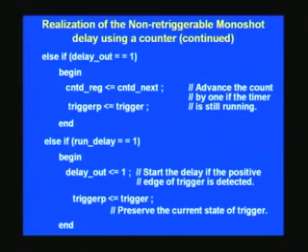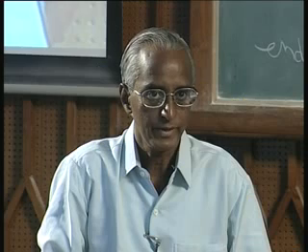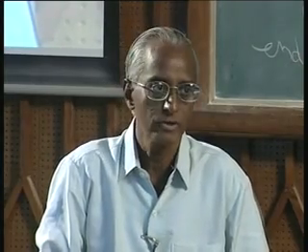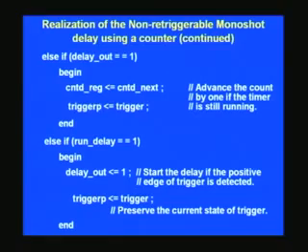So far we have seen how to write Verilog code for a simple D flip-flop, and then went on with a little more complexity by cascading 2 registers, and then we spoke of the non-retriggerable monoshot. And perhaps you can take as an exercise how to do a retriggerable mono. You can amend the code for the existing one. We'll continue with the sequential circuits in our next lecture too. Thank you.